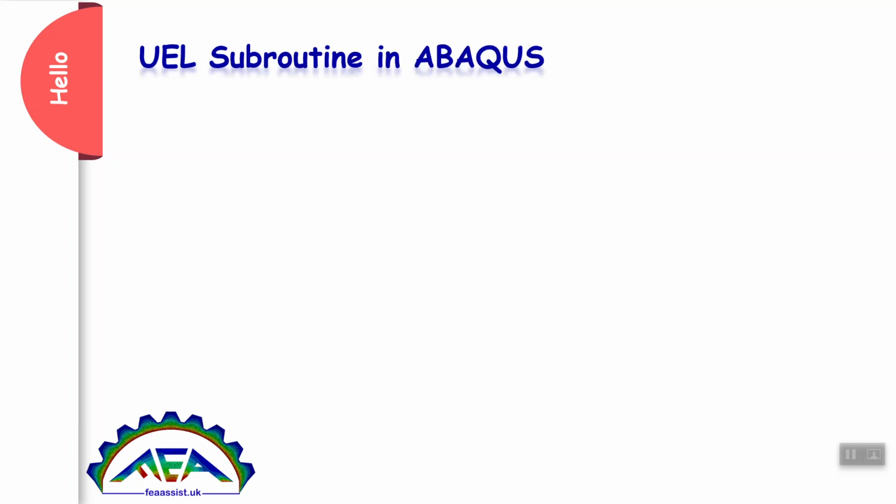Hello. You want to learn UEL subroutine in Abaqus easily and quickly. UEL is a subroutine to define a new element in Abaqus. Consider you have a one-dimensional element with points A and B. For example, temperature in this element is interpolated between the temperature of point A and temperature of point B. So, an interpolation function computes and defines the temperature at any point in this element.